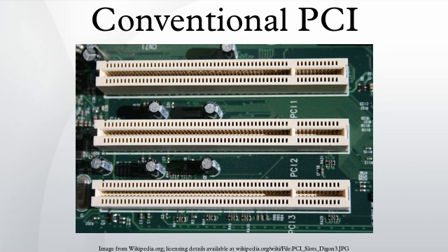Disconnect without data: if the target asserts STOP without asserting TRDY, this indicates that the target wishes to stop without transferring data. STOP is considered equivalent to TRDY for the purpose of ending a data phase, but no data is transferred. Retry: a disconnect without data before transferring any data is a retry, and unlike other PCI transactions, PCI initiators are required to pause slightly before continuing the operation. See the PCI specification for details.